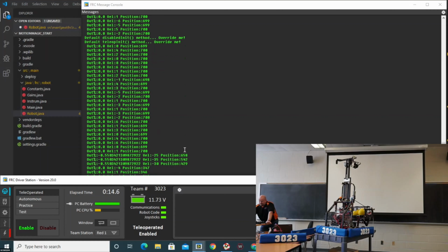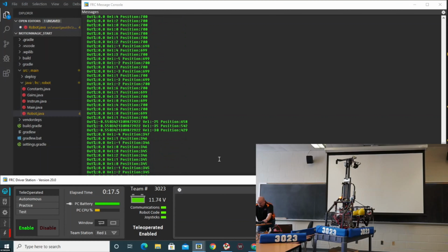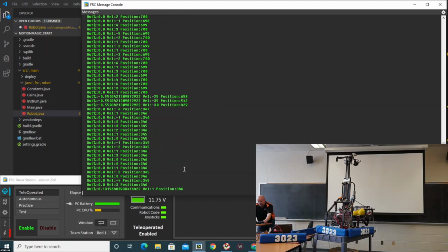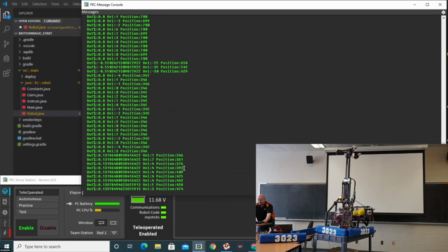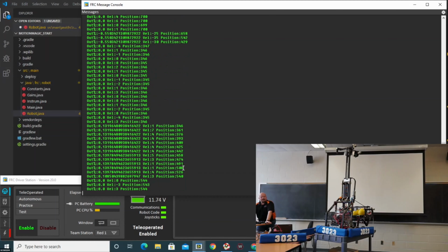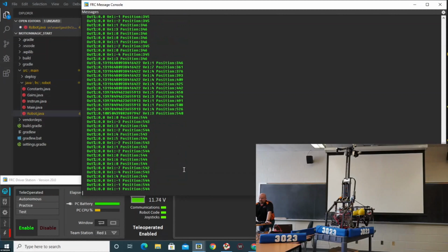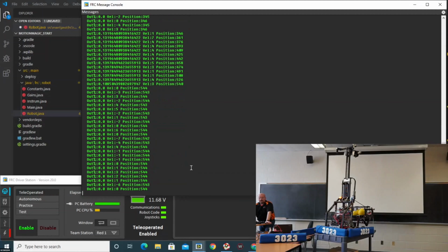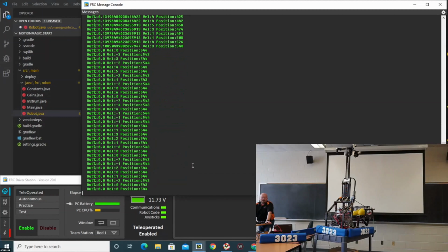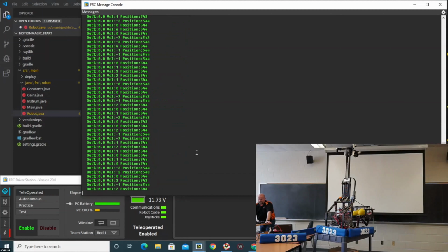So let's try to imagine a little bit that I have to hold this joystick maybe at 0.13 just to hold it in position. Now you're going to want to look at the video I kind of hinted at from 973 back in 2016 on building your mechanisms so you don't burn up motors. A lot of these 775s and the like, if you stall them, they'll catch fire. Now there's a point, VexPro has some charts on their website that show you that you can stall these motors using 2 volts and it'll last the life of the game without burning up. So that's where we try to target that 0.13 or so.